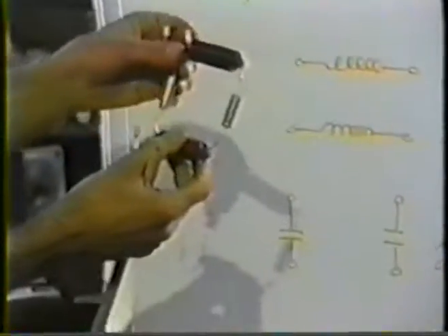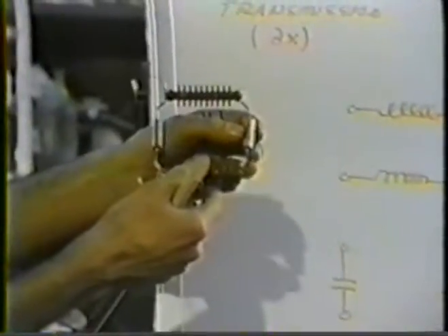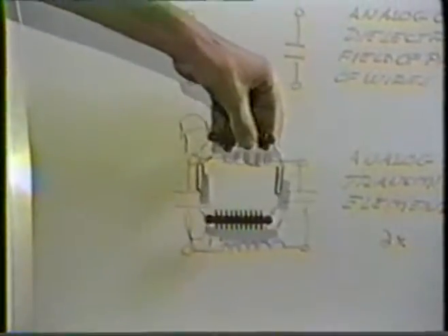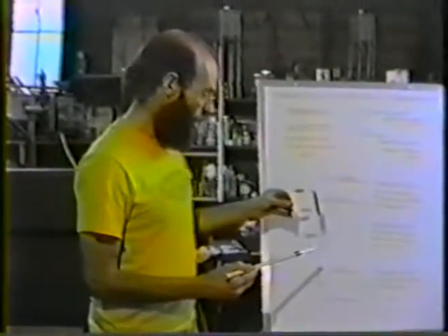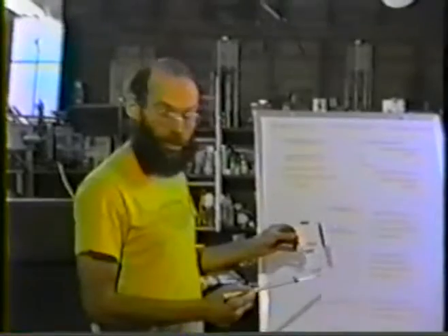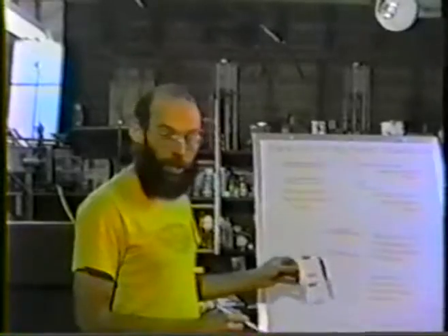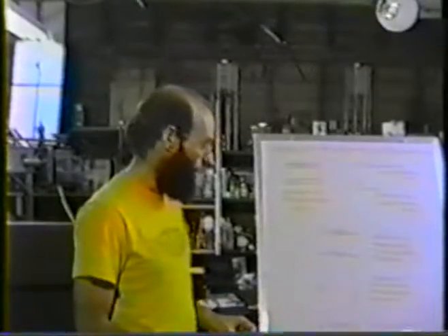And we have some radio frequency inductance coils of 10 millihenries, and we have some high-Q pulse capacitors of 0.047 microfarads. This constitutes one element of transmission. And of course, we can propagate either longitudinally or transversely, and we're going to stack these elements up to symbolize and synthesize these two forms of waves, and then we're going to get in there with some rather unique detectors and some conventional detectors, and even use our fingers and determine exactly what's going on with these things and see how this correlates with our previous measurements of actual transmission structures and not their analogs.